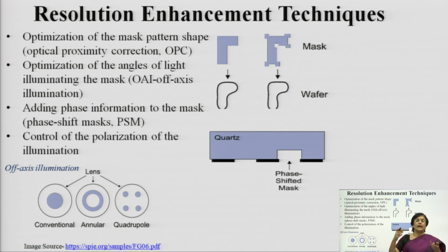So, as an engineer you also know the remedial actions. The remedial actions are mainly undertaken at the mask design level. Whenever you are using a mask with a rectangular portion, the optical source is not going to create the exact pattern. So, you try to modify the mask, creating some extra portions in the mask itself, so that when you are focusing the light, it will exactly reproduce the image.